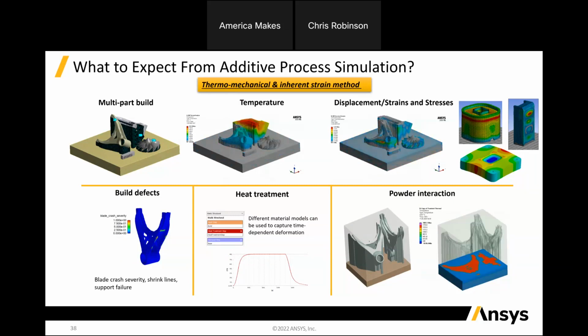If you're trying to look at displacement, strains, and stresses, then it's also going to depend on what type of geometry. Inherent strain is going to be actually pretty good for a lot of bulky parts. In many cases, when you get into thin geometries, you really need those mesoscale adaptations, the scan pattern influence. And especially for thin-walled, multi-wall geometries, being able to utilize the Ansys Mechanical solution, where we have what's called the layered tet mesh. It's a tetrahedral mesh that can conform to your part geometry a lot better than a uniform hexahedral or a voxel mesh can. So it kind of depends on the type of geometry and different things that you're doing.